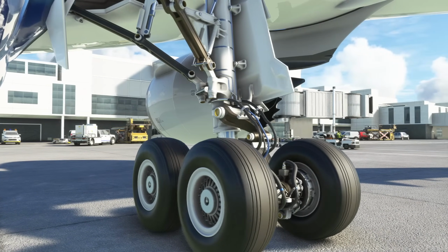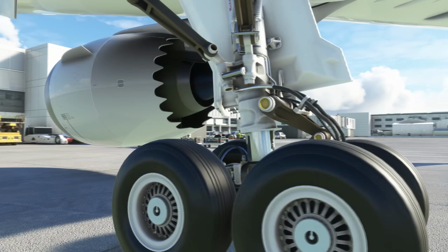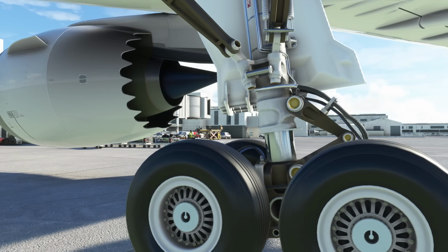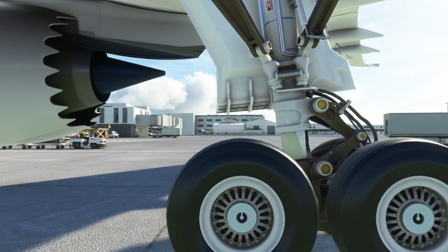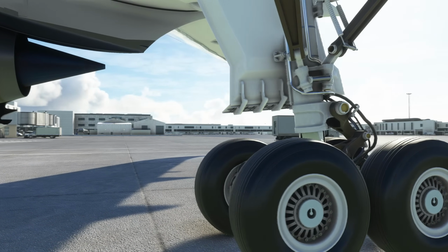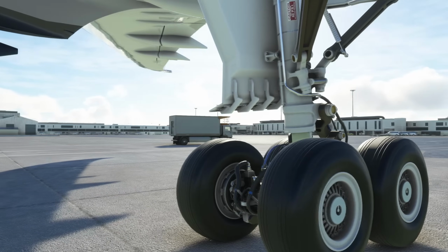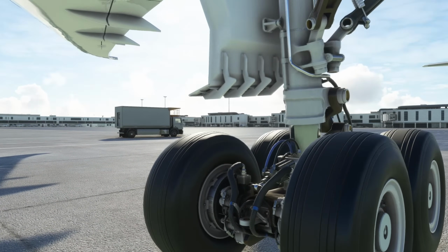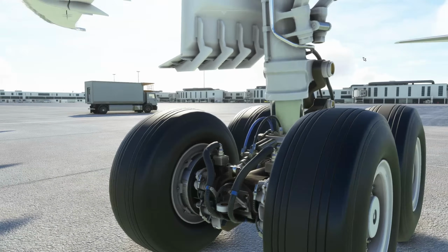One thing that you do get on the 10, which is missing in this visual model, is an additional hydraulic strut fitted to the main gears. It's not something that we're told much about as pilots, but it is fitted. It's used by the 787-10 variant to actually help get the aircraft into the air. It's really quite remarkable, but as you can see here, it is missing. There's a hydraulic addition that runs from here up to here on the main gear, but this is the more standard gear.